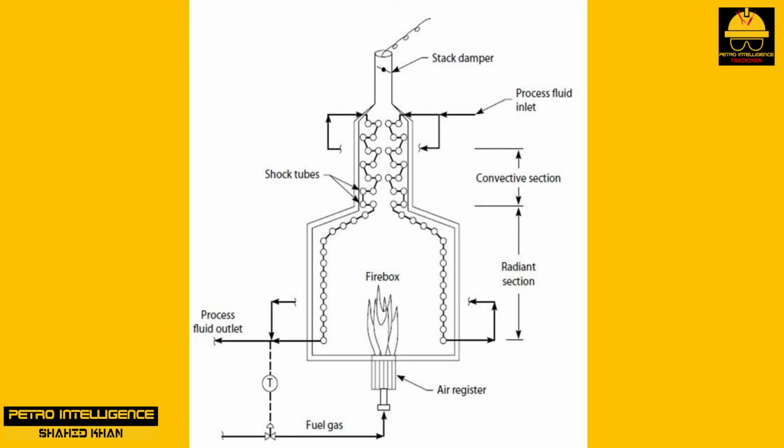As it is much easier to make fin tubes from just one type of metal instead of two, though, the furnace manufacturers will often choose to make the fin convective section tubes entirely out of low chrome steel, in which case one could expect them to withstand temperatures of less than or equal to 1300 degrees Fahrenheit. It is advisable to check what types of tubes you have in your furnace and know what temperature tolerances they have.